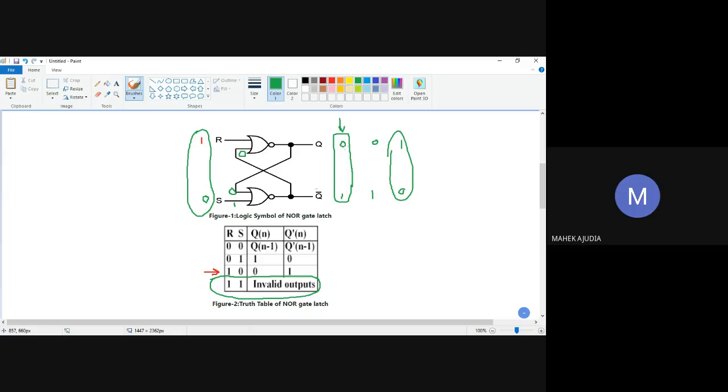What I'm saying is that it is not like your output is always changing its state. The output will only change state if it is not in the reset condition, for the case we are talking about right now. So that's the behavior of memory. That means the circuit knows what the past output was, and that's why it is called the smallest element of memory. Whatever output Q comes here is kept stored until you give the next input on the input side, R and S. Is that clear? Yes, it is. Okay, I hope everyone is getting the working of this RS flip-flop.